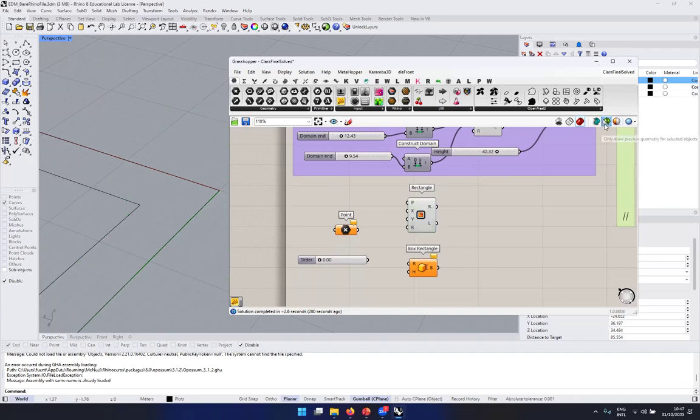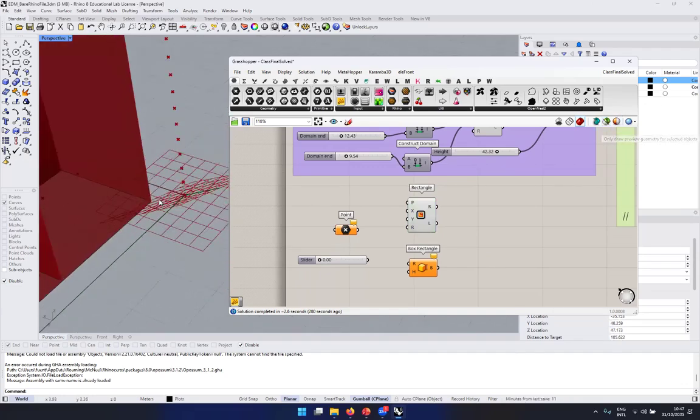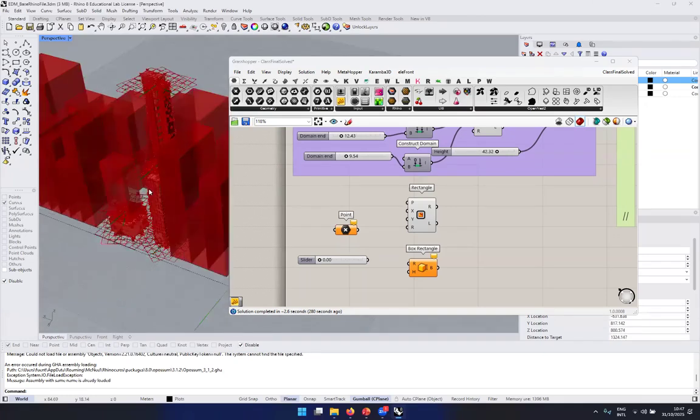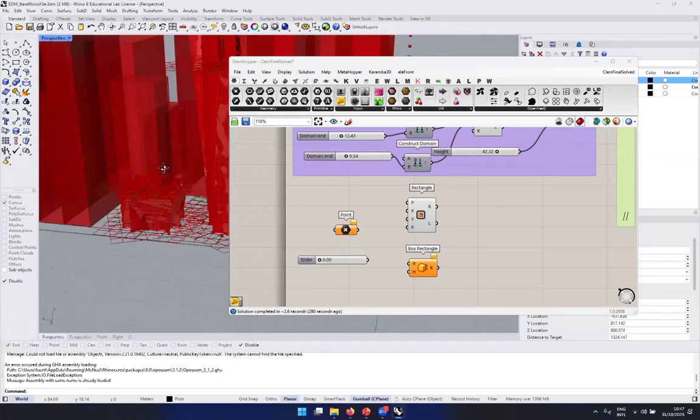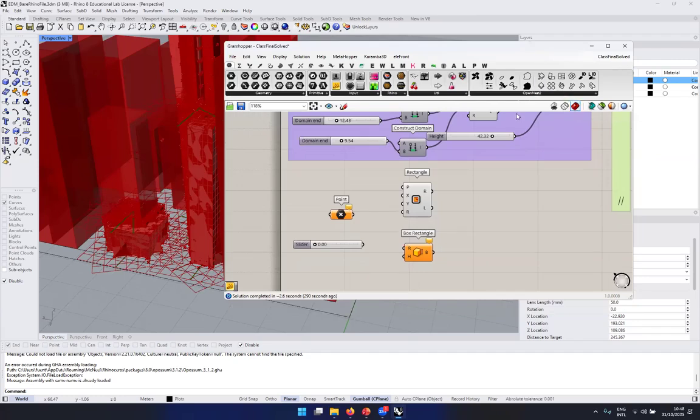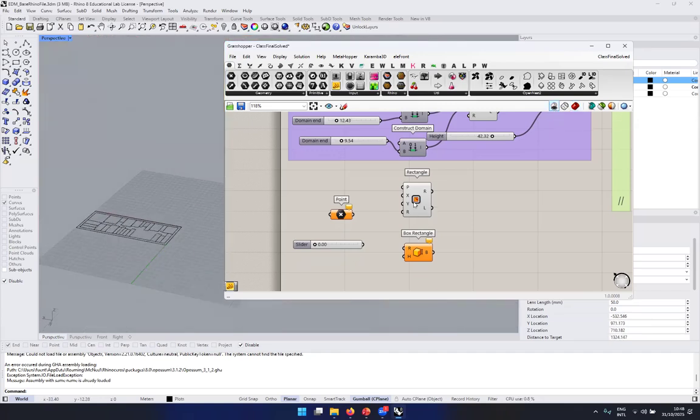So the problem is that when you have long definitions like mine, it will be a bit messy. You will see a lot of stuff here, and it's not easy to control. You need to handle display. Display is really easy in Grasshopper. Everything is here. Let's start from the left. This icon here means I don't want to draw any preview geometry. I want nothing. So my Grasshopper is completely blinded. I see nothing in Rhino.